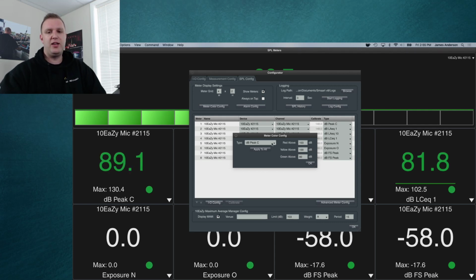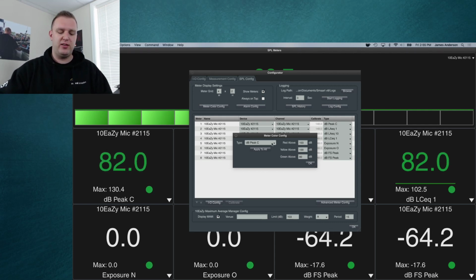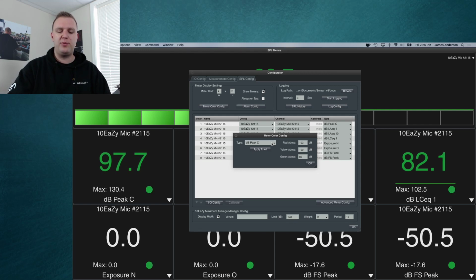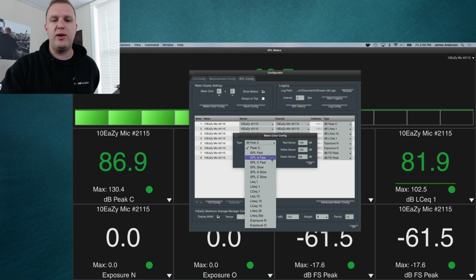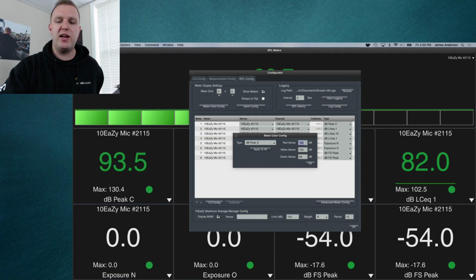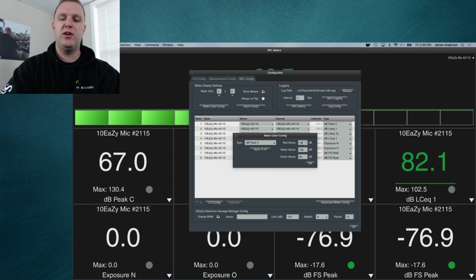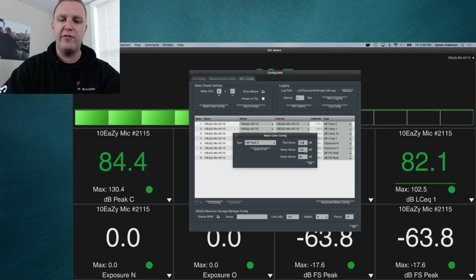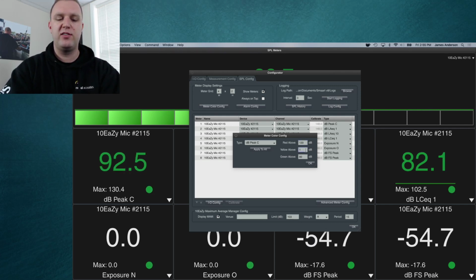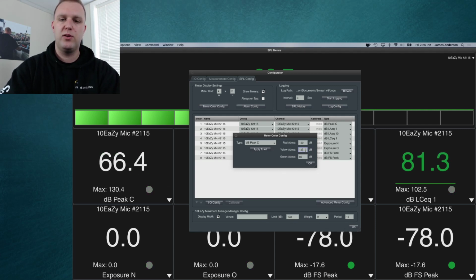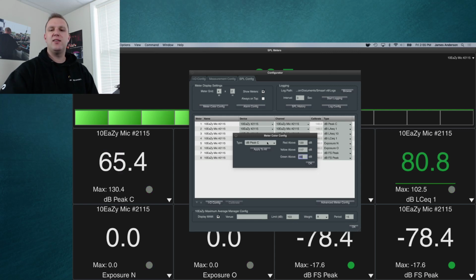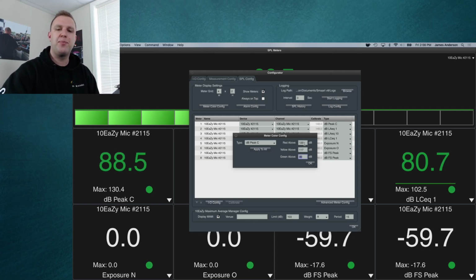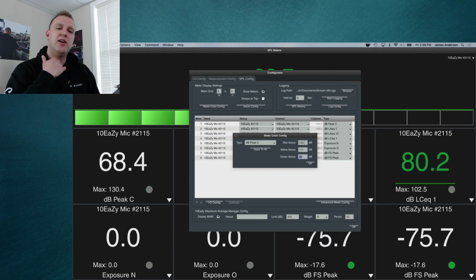So a common thing you might want to change is, for the SPL types that are letting in more low frequency, like peak C or C weight, no weight, maybe you change the red above to be a bit higher, so they're not just constantly in red during your event, and say maybe they turn yellow just below as a warning. So 3 dB below that, and then green above 80. Okay, so this peak C measurement is not going to turn red until we get to 120 or above. This is a really handy thing.